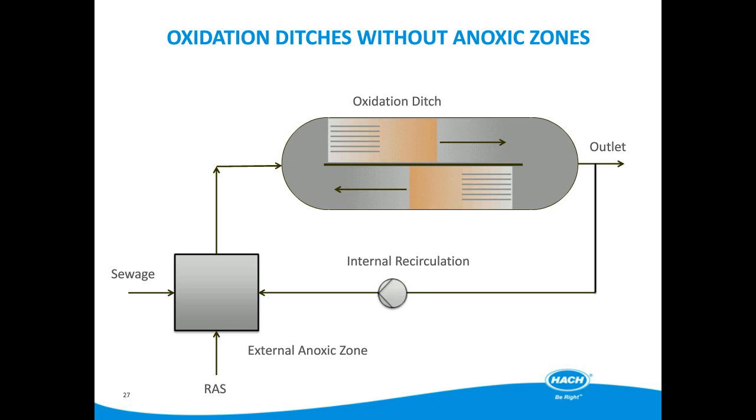There should always be a bit of headroom, especially if you've got a site that's subject to shock loads, even in oxidation ditches, which tend to even those out. You want a bit of headroom to allow the system to balance out after it's been hit with a shock load.